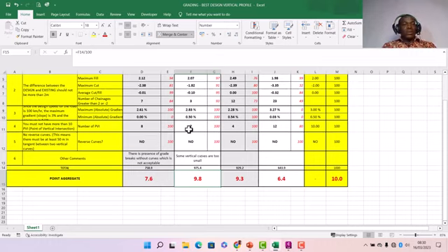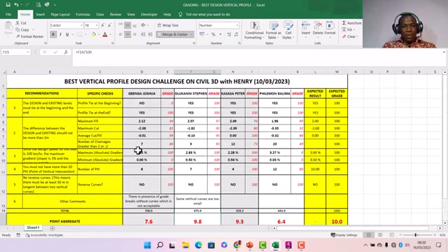You have constraints when you are designing, so you have to follow those constraints so that you have a good design at the end. If you can just see here, for instance, in the maximum grade, all of them, except Philemon, were within the requirement. And in the minimum gradients, we have two people that observed that. I see that Benga Joshua had 0%, which is not practicable. You shouldn't have a road that is 0% just going flat. We might have some cases like that, but it shouldn't be too bad. If you have side drainages, for instance, what is the slope? It's not going to work.